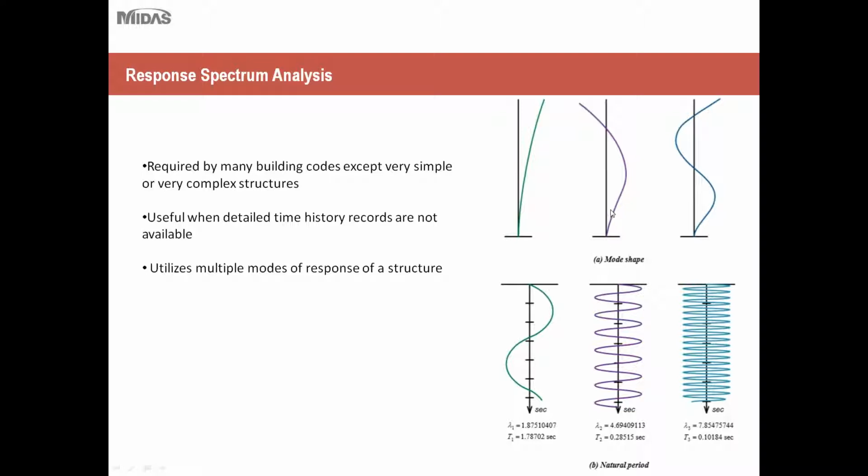Some of you are probably wondering what these pictures represent. When you're doing a response spectrum analysis, you'll have several modes that you'll be studying. Each of these pictures below represents a different period of the wave. For example, let's say the earthquake just starts, and this is what the vibration looks like, and this would be the mode associated with it. However, when the earthquake picks up, the frequency, intensity and strength might increase, and then you would have a different modal shape.